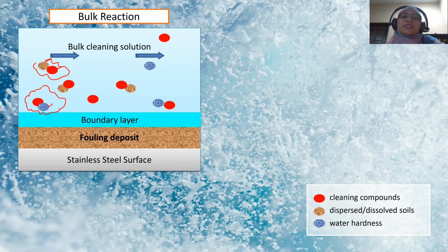That's why a pre-rinse step in cleaning and a good quality potable water supply is important. If the water hardness condition is not good, you need to choose a detergent which has complexing and sequestering agents.